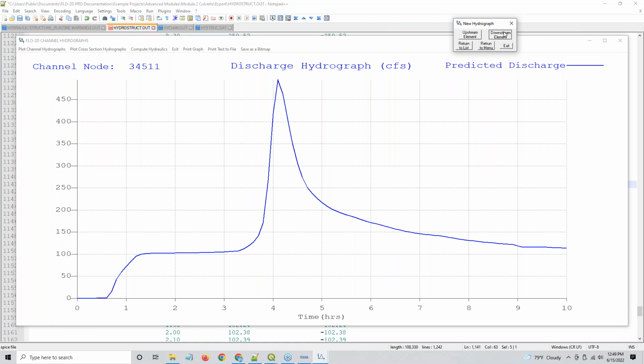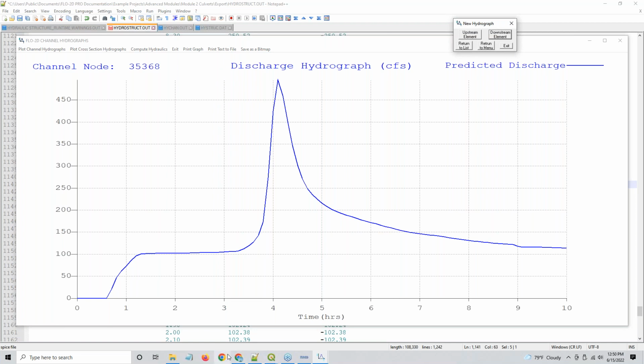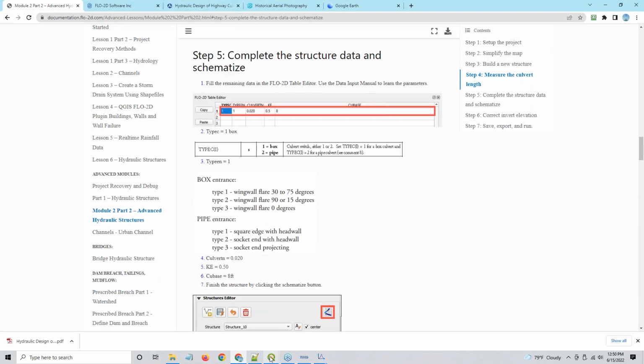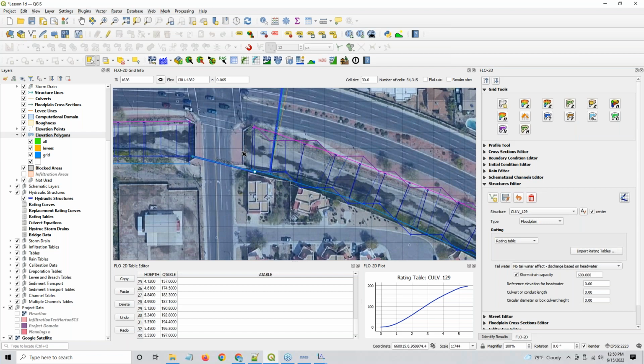And then if I go downstream, you'll go through the structure. And what you don't want to see is this getting super spiky right next to a structure because the structure geometry doesn't match the channel geometry. So if you start seeing spikes coming up to and going away from a structure, it's very likely that the cross-sectional areas leading up to that structure are wrong, and you're probably just drawing this rectangular or trapezoidal cross-section all the way up to the structure.